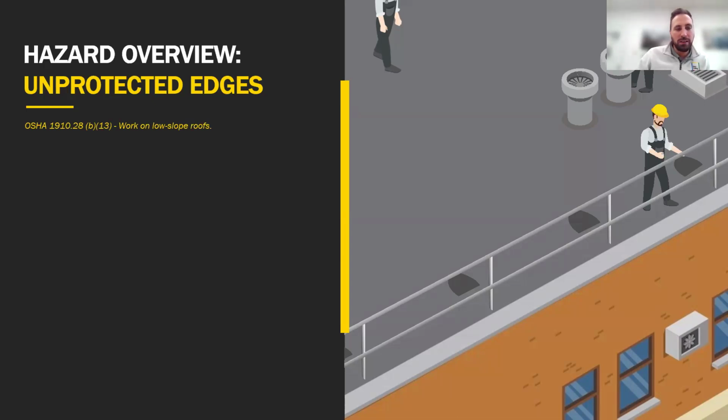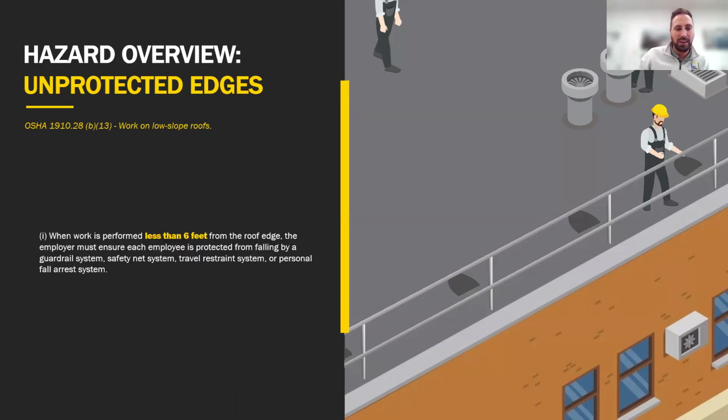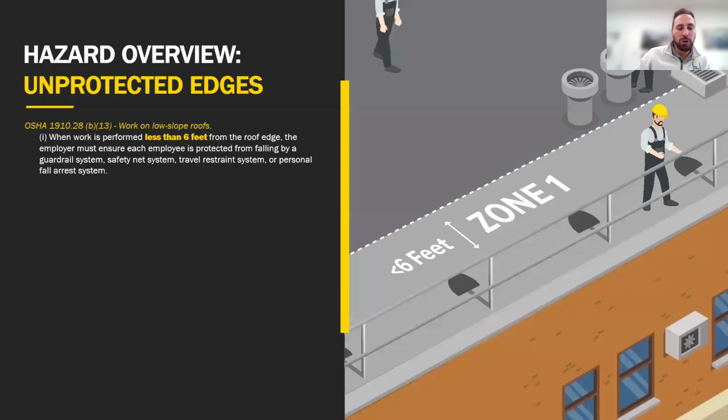So OSHA 1910.28 B13 states in part 1 that when work is performed less than 6 feet from the roof edge, the employer must ensure that each employee is protected from falling by use of guardrails, safety nets, travel restraint, or personal fall arrest systems. So what that means is, if I'm working in this area, I need to have some form of fall protection, whether it's guardrails, nets, anchor points, and restraint or arrest. OSHA doesn't care, but this is the most critical zone that we need to keep workers safe in.